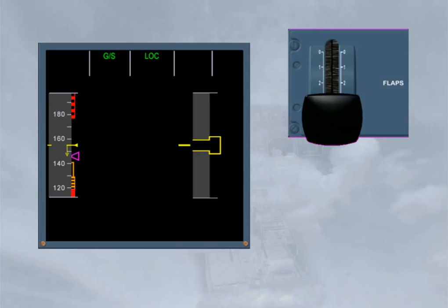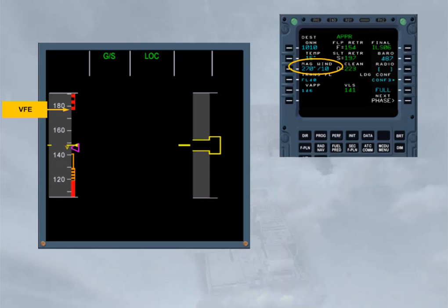According to the wind conditions, which may vary during approach, the target speed will be adjusted between the V approach and the VFE of the related flaps configuration. The wind, which has been entered on the performance approach page, will be used to compute a minimum energy level. This minimum energy level relates to the ground speed the aircraft will have at touchdown and is called ground speed mini. There are indications associated with speed and angle of attack protections. These protection indications will be discussed in the flight control modules.